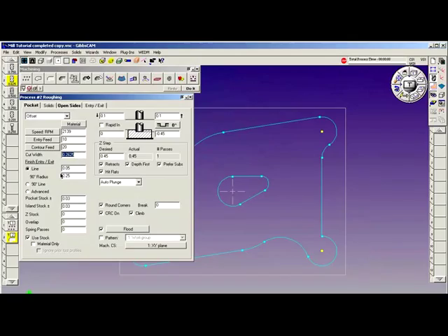Entry exit moves. In order to use cutter radius compensation, you must have an entry line. Now, an arc is not essential, but you must have an entry line to instate the G41 or G42 command. An entry radius is the ability to arc onto the cut and keep the pressure off the cutter on the initial entry move.